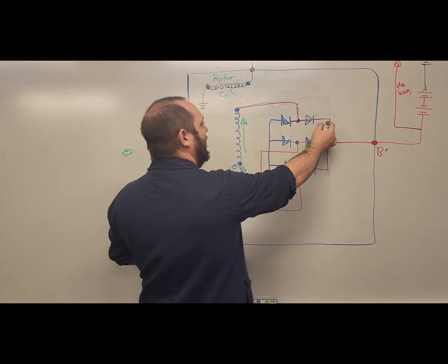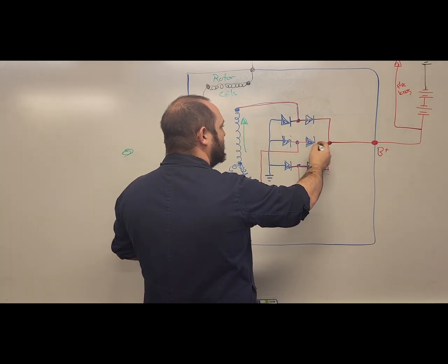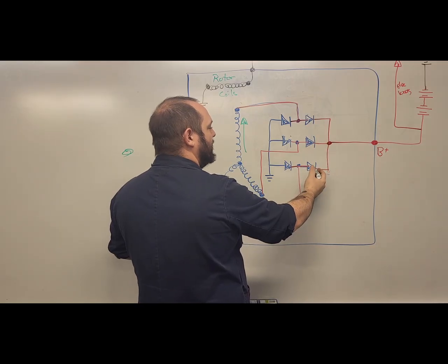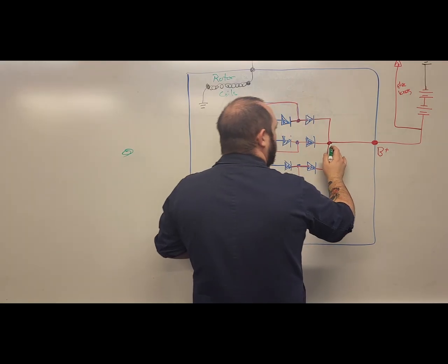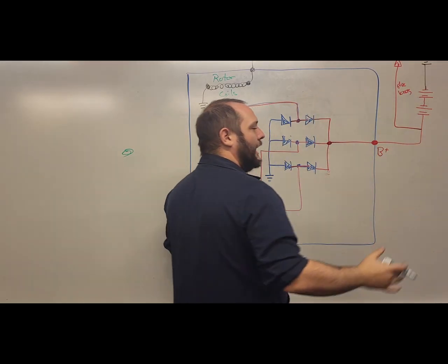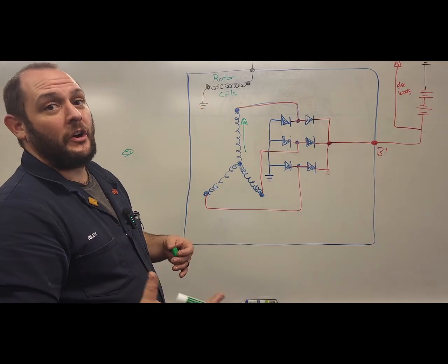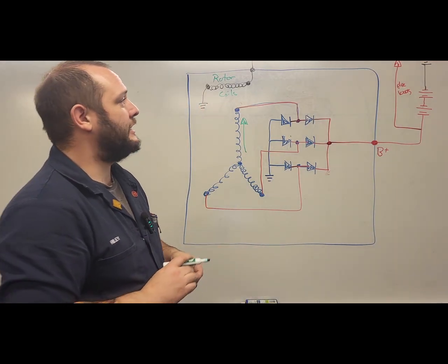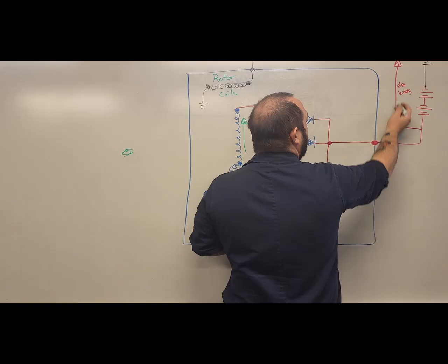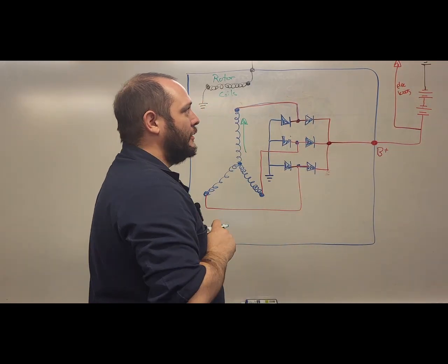We're on the anode side of this diode, so it's not going to open up these diodes. These diodes are going to be deactivated. That current will flow out, charge my batteries, maintain my batteries, put a current through my batteries in the correct orientation, run that current through any electrical loads, and go back out to ground.